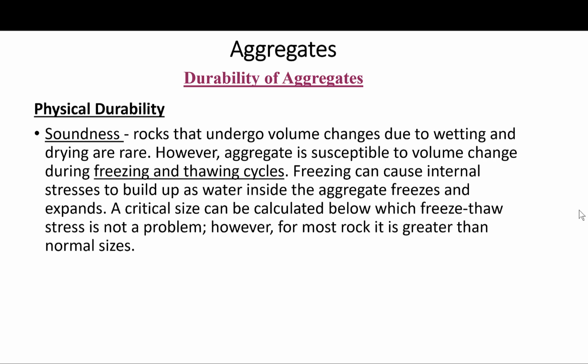But aggregate is susceptible to volume change during freezing and thawing cycles. Freezing can cause internal stresses to build up as water inside the aggregate freezes and expands. Basically, a critical size can be calculated below which freeze-thaw is not a problem. However, for most rock, it is greater than normal sizes.